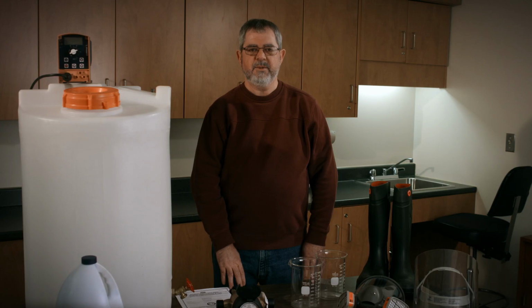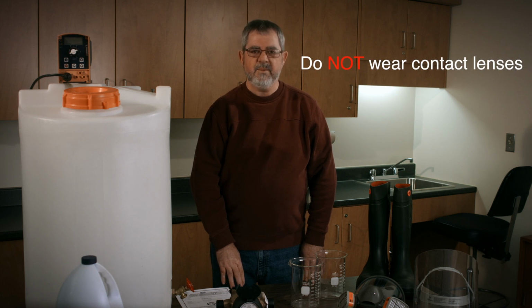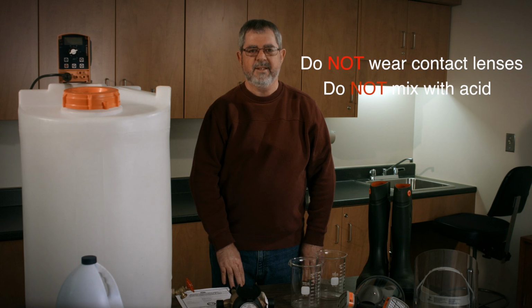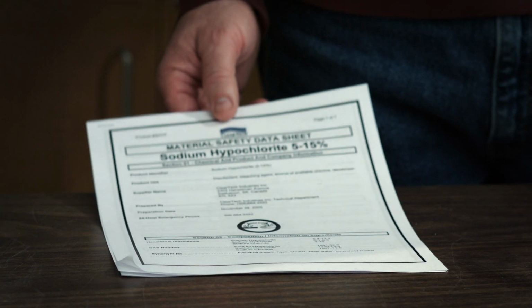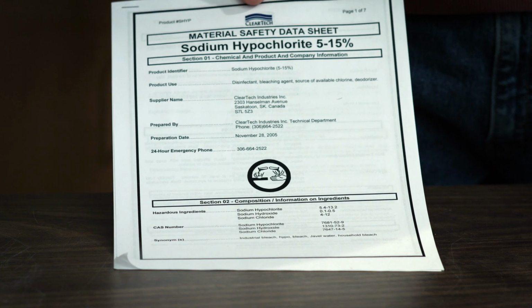The mixing area should be well ventilated and equipped with a shower and an eye wash station. Contact lenses should not be worn when handling sodium hypochlorite, and it should never be mixed with acid as the chemical reaction will create a toxic chlorine gas. Take time to review the safety data sheet for your own sodium hypochlorite product before use.